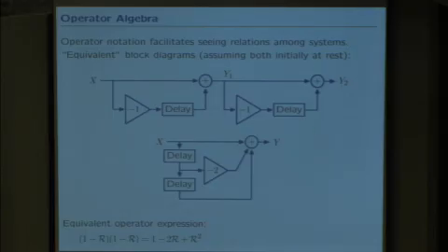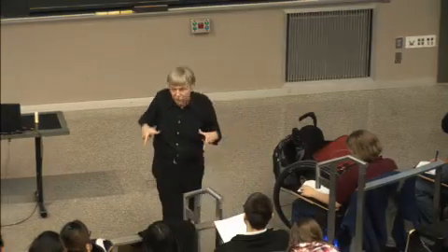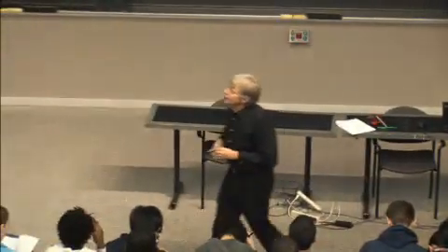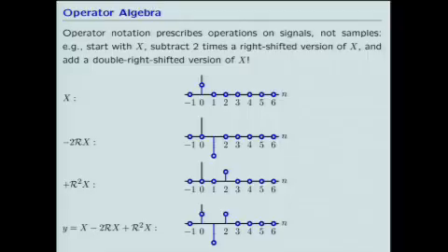The "provided" is important. Obviously, since they have different delays in them, if the delays didn't all start out at 0, the differences in the delays could propagate into the output. So all of the statements that I'm making are premised on the idea of initial rest. The other important thing to remember about operators is that it's a higher level abstraction. We can think about the operator as composing things, but the things that are composed are whole signals, not samples.